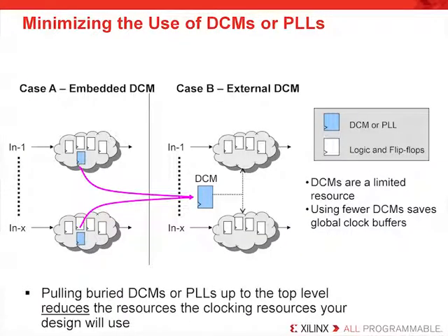One of the most common misuses of the clocking resource is instantiating components that already have DCMs, PLLs, and global buffers, that is BUFGs, already instantiated as part of their netlist. So always evaluate your use of the clocking resources, particularly for instantiating lower-level netlists, to make sure that you completely design out all the unnecessary or duplicate resources.